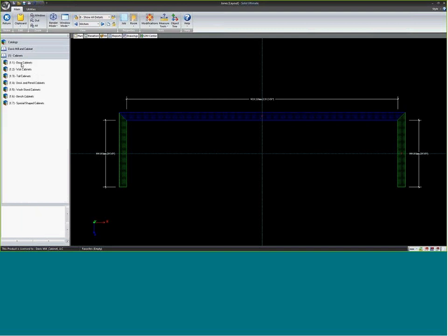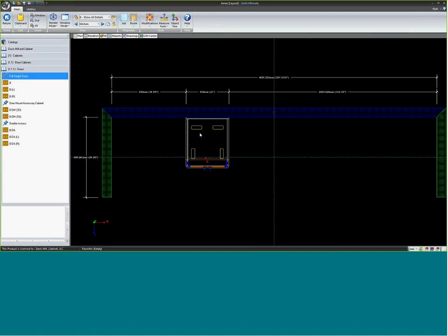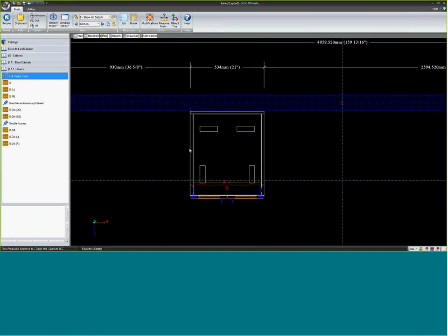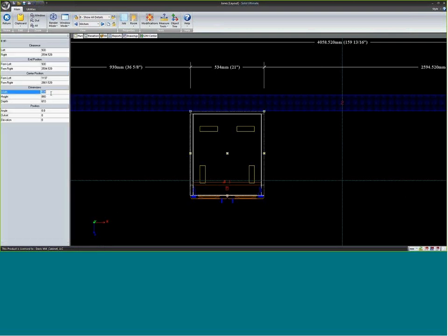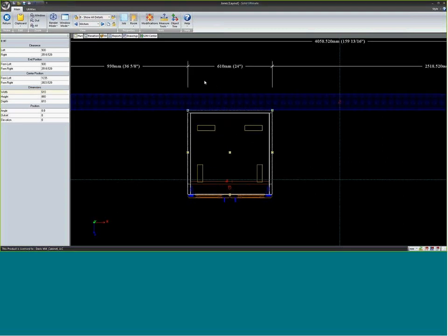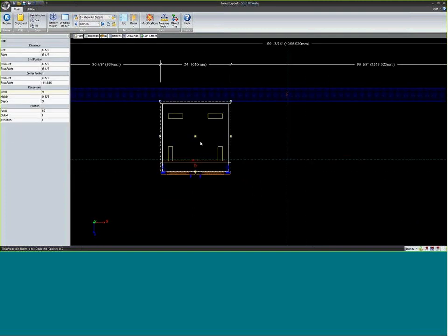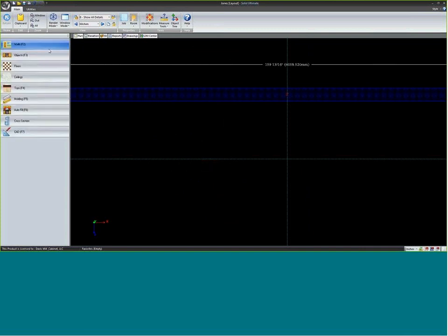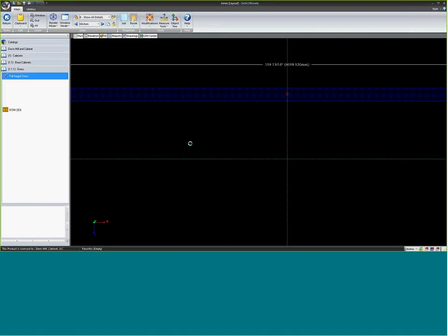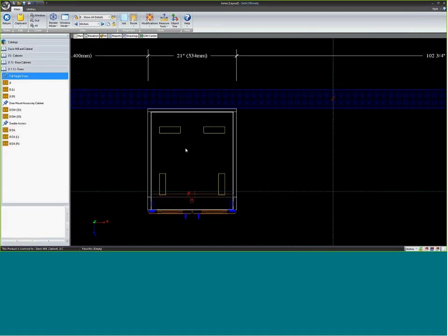The issue here is in converting things between imperial and metric. If I get a cabinet box and drop it on my screen, it happens to convert exactly to 534 millimeters. It converts exactly, but if I were to switch to inches, it looks like I've got 21 inches, 534, just like we had before.